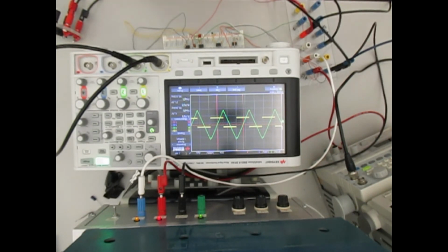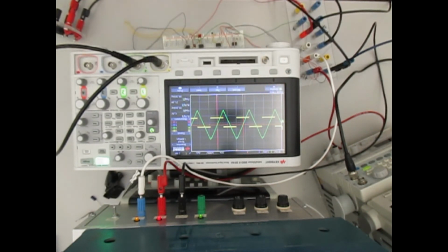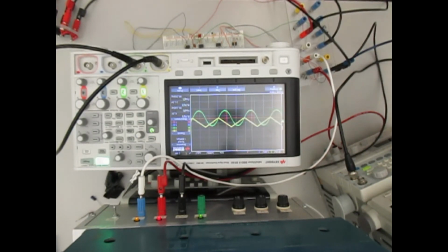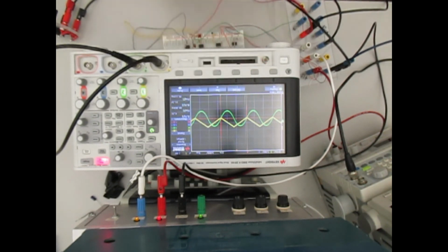Okay, now, here's the square wave input, and we get our triangle wave output, and that's what we should be getting. There's a little glitch up here, and that's probably just, again, a bit of a wiring issue. So it's not a big deal. But actually, that's working quite well. Okay, so then if we go to the triangle wave, we should get a sine wave out. And you can see there's my triangle wave input, and then there's my sinusoid. It's a little rounded compared to what a normal sinusoid would be, but it's actually pretty good.